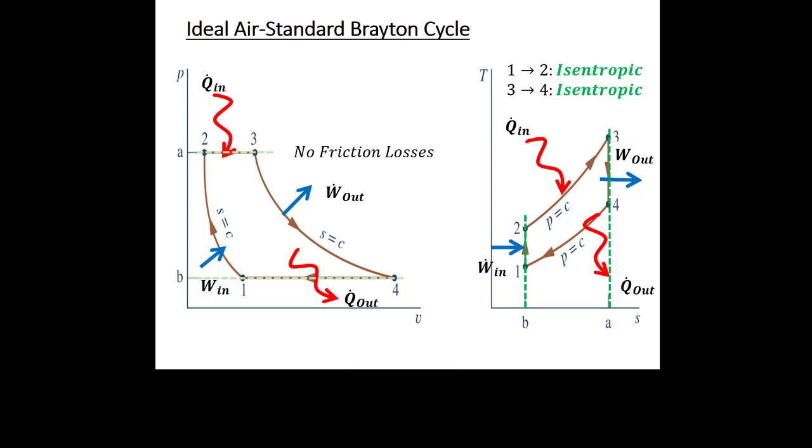Now, the key to any process where the working fluid is air, when you start to fix states, you have to know where the isentropic processes are, or at least where they could be if everything was ideal. And those will be the components that have to do with power generation or power consumption. So as you go through a turbine or a compressor, those have the potential of being isentropic. Those are the places you're going to use some equation with k in the exponent if it's constant specific heat, or some equation with PR or VR in it if it's variable specific heat.